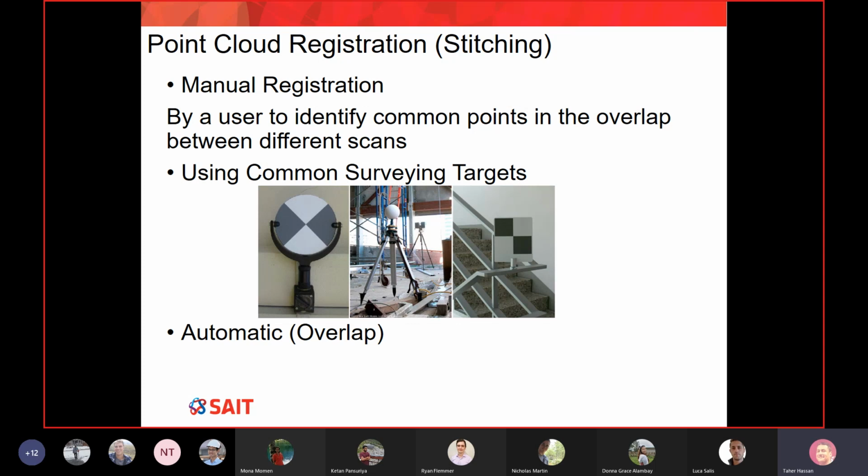Is that good or bad? Can I ask you? If I have 4 point clouds, a million points here, a million points there, but every million points follow a different coordinate system. Good or bad? Bad. Okay, so how can we solve this puzzle? We want all my site in one coordinate system, so at least I can measure the relative location in the right way. Otherwise, you cannot get relative information because every scan has its own coordinate system.